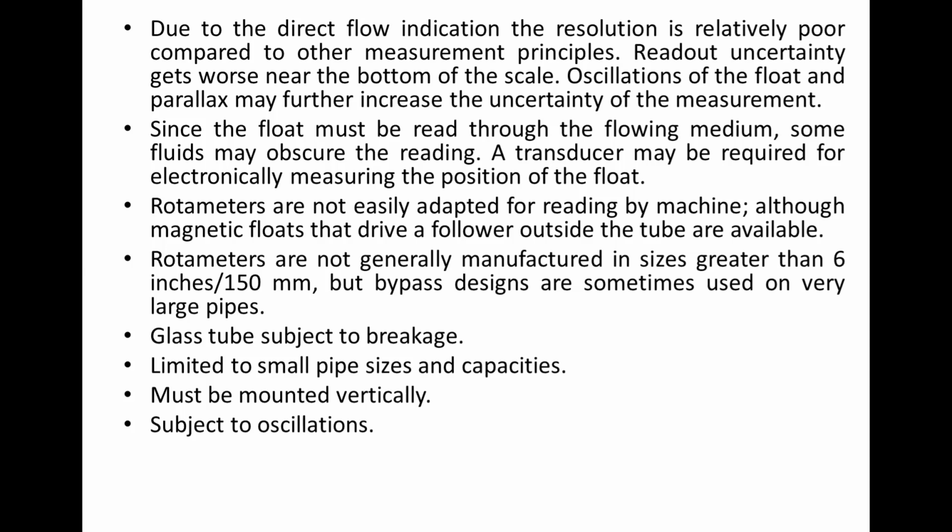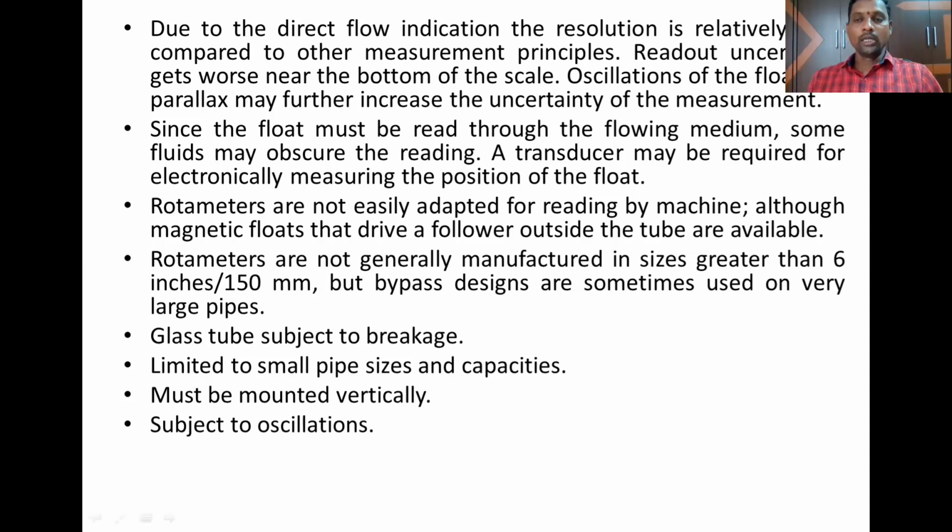They are not generally manufactured in sizes greater than 6 inches or 150 mm. Sometimes the glass may be subject to breakage after a certain period of use. They are limited to small pipes and capacities, always to be mounted in a vertical position, and may be subjected to oscillations.